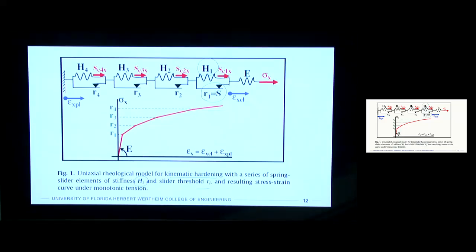And so they have a stress, right, in some dimension, and there can be some elastic strain along that dimension. And that's just represented by a spring with sort of properties E, right? And then when you get into the plastic strain, this epsilon x in the plastic domain, that's where you start to get these unrecoverable changes that contribute to the damage.